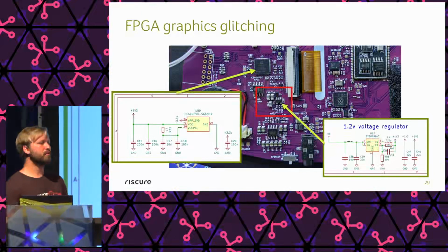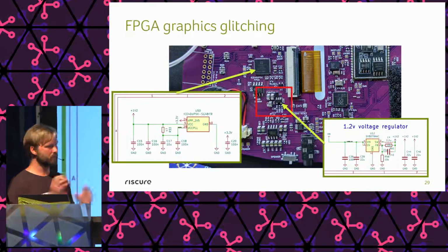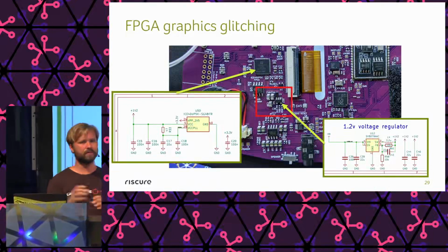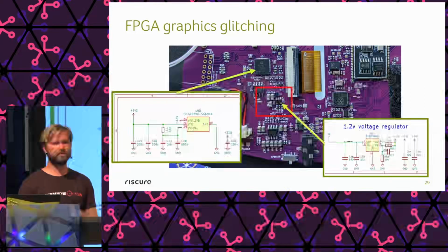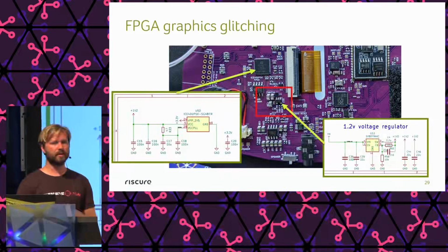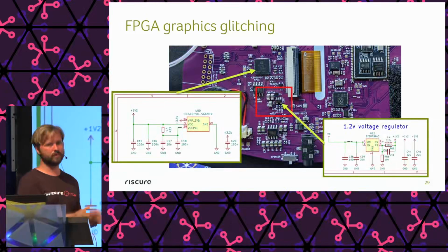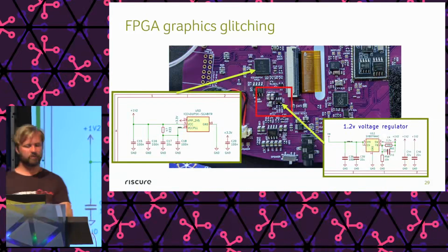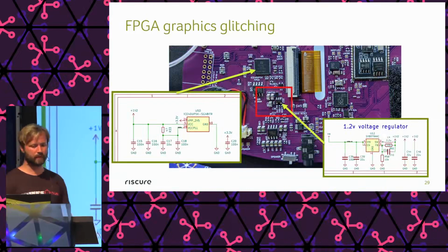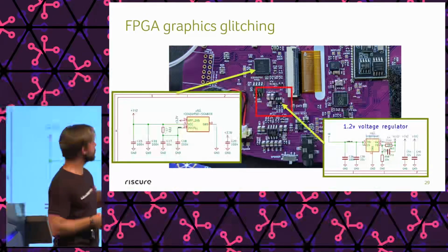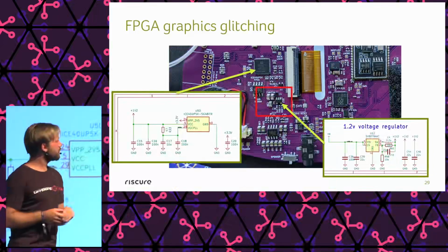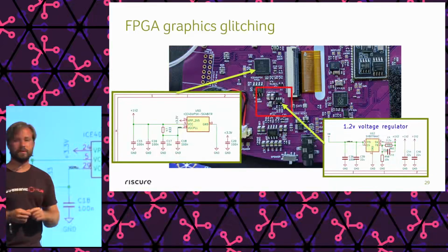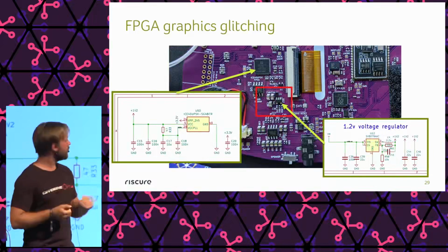What often also happens with fault injection, instead of targeting the chip itself, you often can, for example, introduce a glitch in a capacitor next to it and affect it through the voltage, introducing first EM and then causing a voltage change in the capacitor. So we found that if we target this area, marked in red, we can really affect the chip and get different outputs.